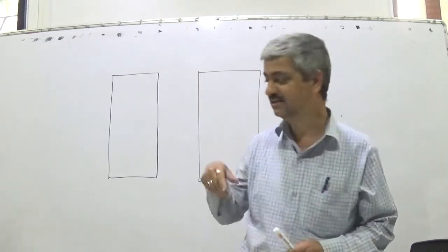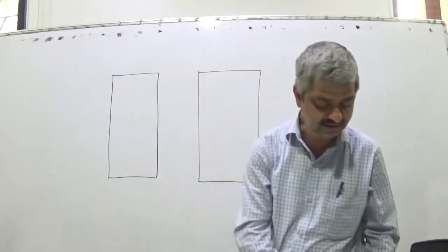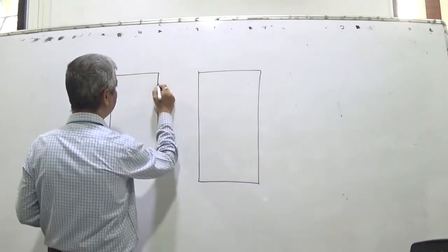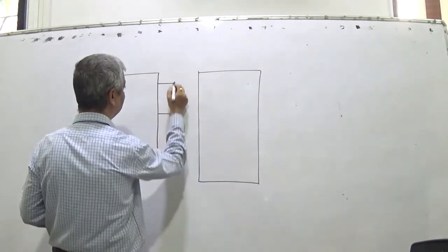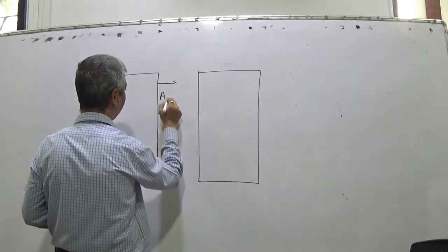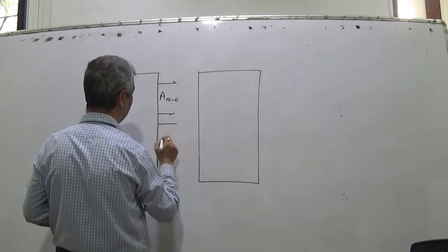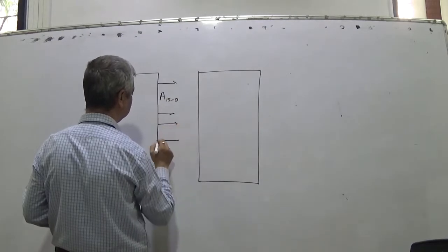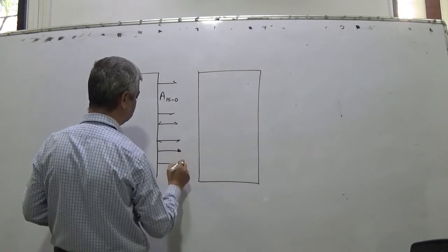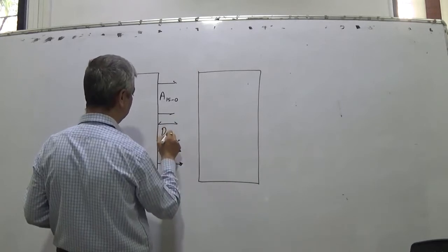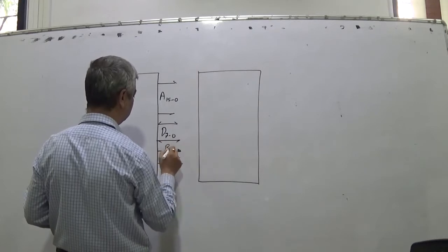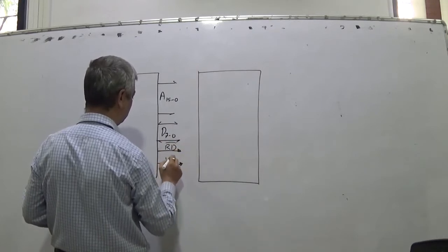So externally speaking, the microprocessor has 16 address lines, A15 to A0, 8 data lines, D7 to D0, and 2 control lines, read bar and write bar.